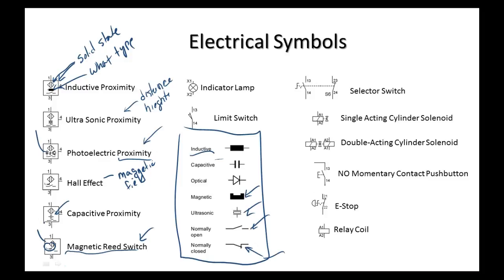What's nice about a Hall effect is that usually, sometimes, you can set the sensitivity on a Hall effect. You can't set the sensitivity on a reed switch, because a reed switch is electromechanical. But it still senses a magnetic field. Well, that's what we think about. A Hall effect, you would put either north up or south up. It doesn't really make any difference. Well, that's not true. It depends on what type you've got. So a lot of times a Hall effect, we call it a latching.